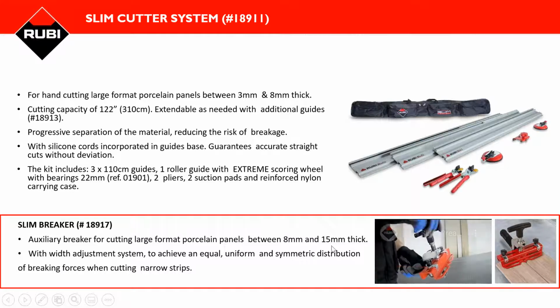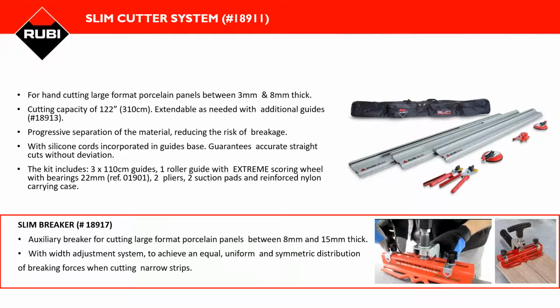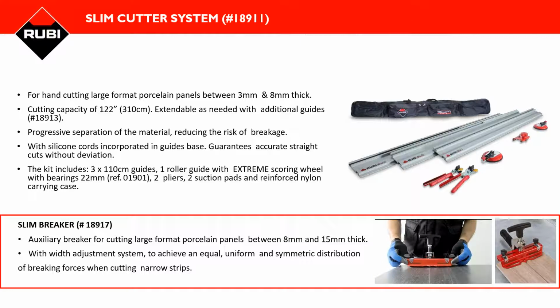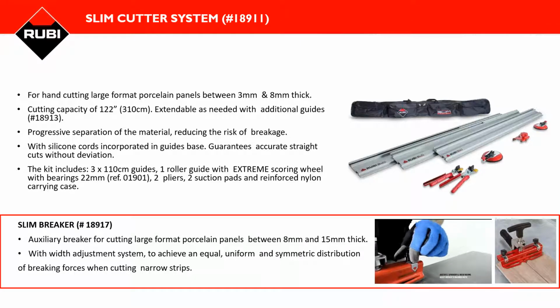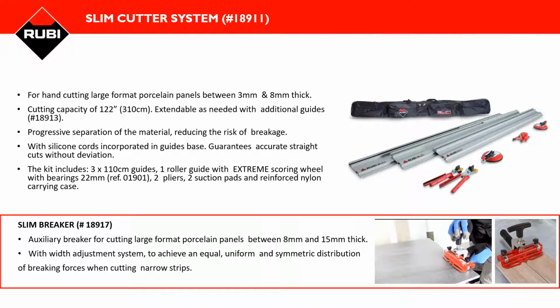Okay. Here we are measuring, we got about 11.2 millimeters. And it's a simple function. You just find the center, it goes through that little triangle. You put the weights out as far as you can, and you just twist until you hear a pop. Once you hear a pop, you can go to the other side and repeat the process. You don't have to do it at the same time. You don't need to get 2 of these slim separators to do so. But once you hear the pop, you just keep turning until you get the complete break. All right?